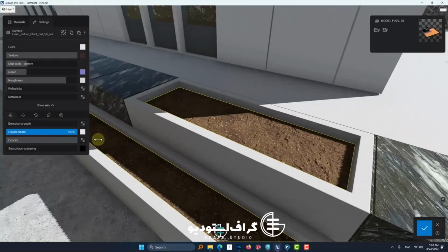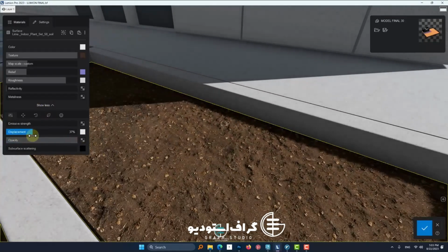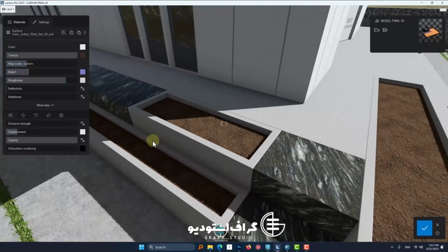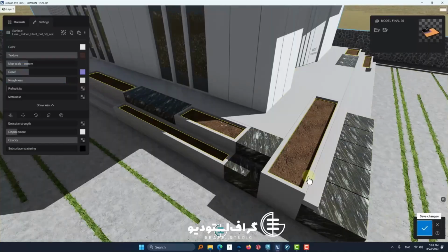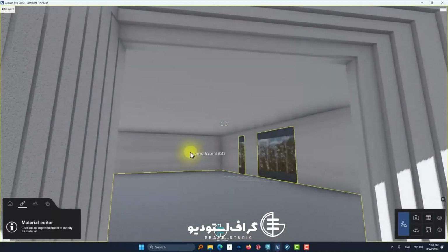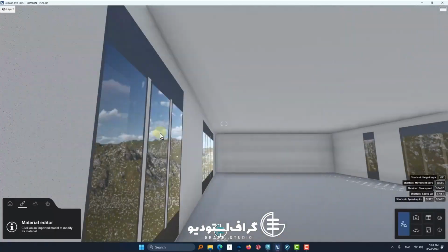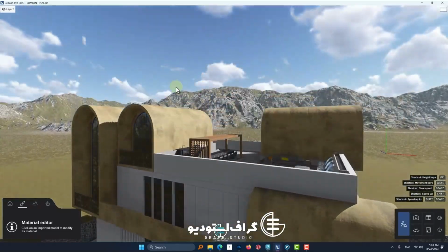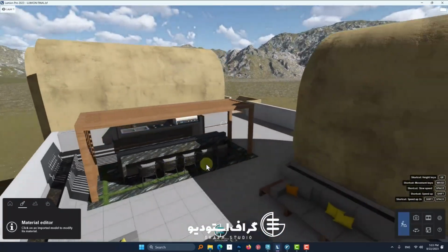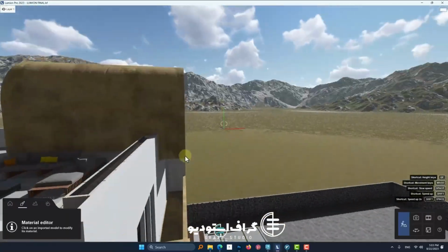I think we should give this one steel. Go to metals. Where did it put the steels? These are all mesh netting. You can assign a metal mesh. I go to the second page. I assign this one. I make their scale finer. Excellent. And you can make it glossier. I reduce the roughness and increase the reflective. Wonderful. That's that. We also have an espresso machine.